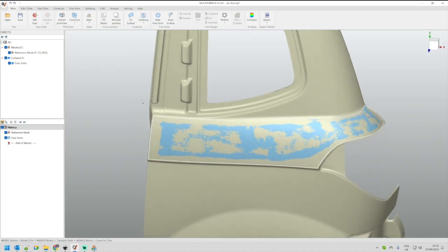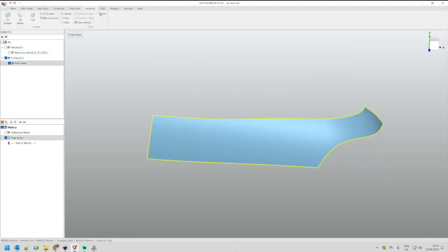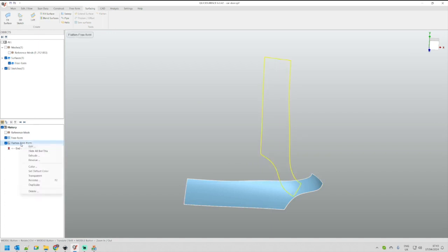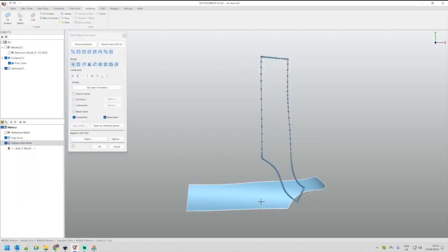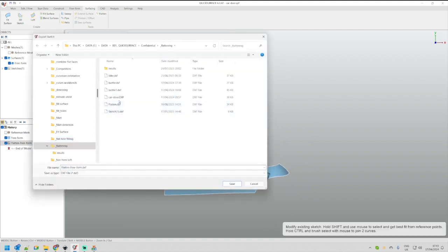Now, as we have this closed, the next step, if you remember, is to select this one, go to surfacing, and then press flat. You can see that the software took this information and unwrapped and created this as a 2D sketch. I can just go and edit now. This is my result. Here you can just again export this as a cardboard shape,